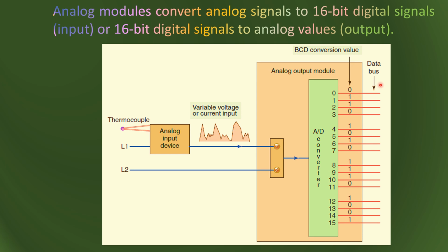Here you should note one thing, that whatever the input device data is, when we bring it inside the PLC by move instruction, fundamentally we are converting the voltage to digits. The standard is most often from 0 to 5 volts, and in some cases it is 0 to 10 volts, and 0 to 12 volt data acquisition systems also exist.